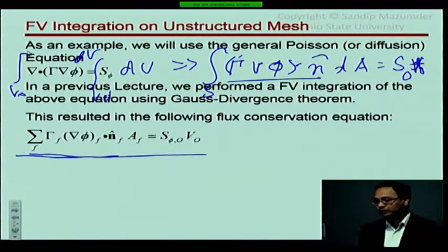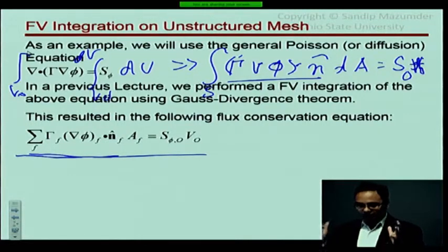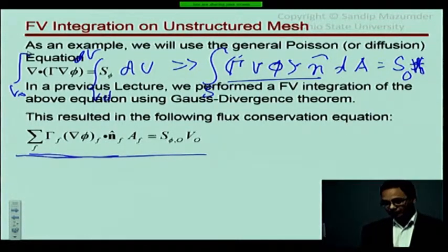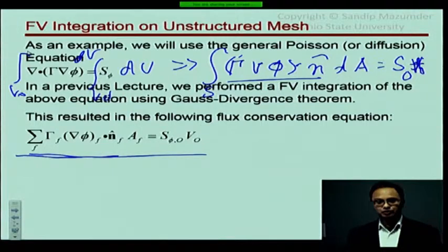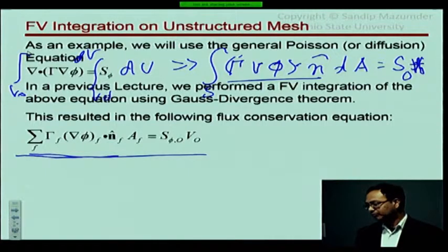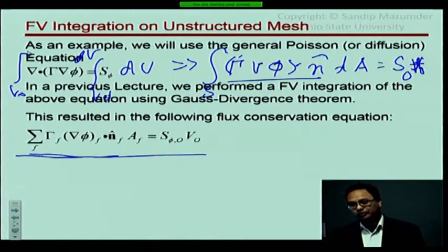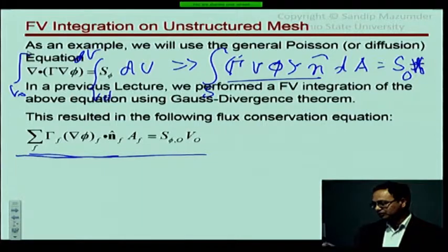Okay, so this is the general finite volume equation that we always start with. It doesn't have any approximations whatsoever other than the fact that the faces are discrete straight faces. They're not curved faces. But no approximations in terms of what shape control volume or how many dimensions, 2D or 3D, or how many faces the control volume has, any of that. So we're starting from that.